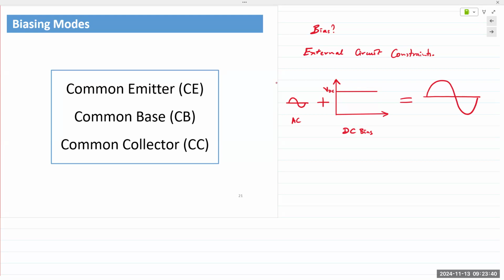I like to state this in 2 ways, and both ways work. Meaning the BJT or the amplifier is taking the small AC signal and adding the energy of the DC source to make it larger. Or the other way to explain it is it takes the DC, it's a flat DC line, and gives it the shape of the AC input signal. Does that make sense? Yes.